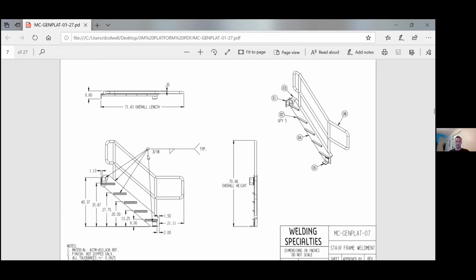Welding all around is stronger and it looks cleaner and you don't leave gaps and cracks. Maybe you only needed to weld two sides of that plate because that's all the strength that was required. But unless there's maybe a cost reason, you should have a really good reason for not just welding all the way around, in my opinion. You don't leave places for rust to develop. Water gets in there and freezes, and all kinds of things can happen when you leave small unwelded seams.